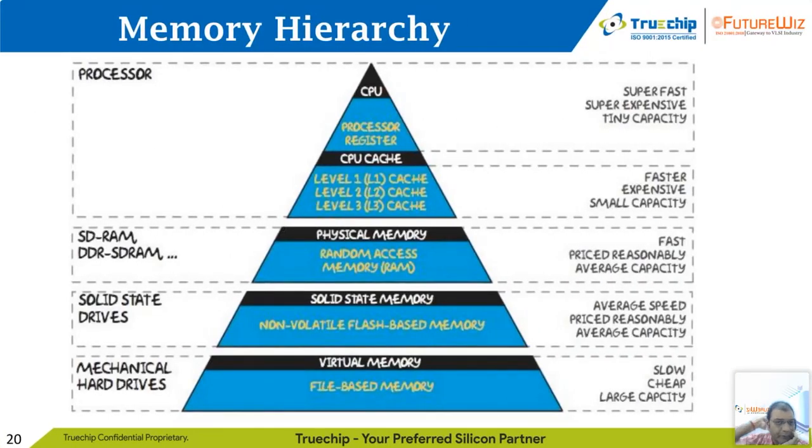Okay, here is what we look at as a memory hierarchy. At the top you see the CPU, then there is a processor register. These are the registers of the processor, which are very fast to access. This is also static RAM typically, or maybe created by flip-flops. These registers are like the registers of the ALU inside the CPU, and they are natively available for the CPU processing to access these register values.